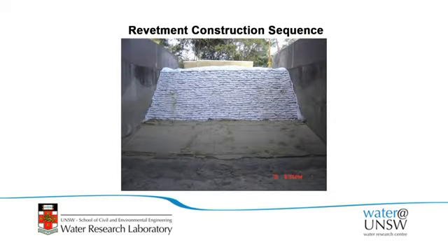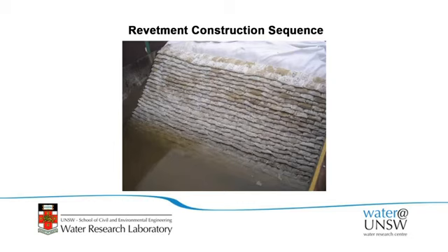This is the beach in front of the structure, and we varied the slope on that, as I said, from 1 in 5 to 1 in 10 to 1 in 20. But as you move out into deeper water, traditionally on the east coast of Australia, you've got about a 1 in 50 slope once you start going out into the deeper part of the surf zone. But the upper part of the beach is much steeper than that. So that's what it looks like in the flume.